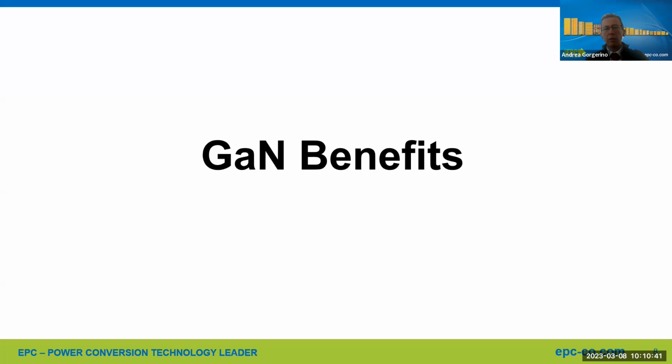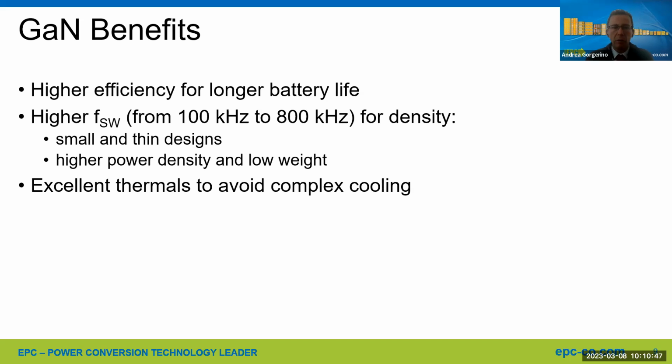All right, so let's dive into some of the GaN benefits for this particular application. I'm going to start off with some high-level topics here. One of the main benefits that I mentioned, one of the requirements from users, is longer battery life. And by having higher efficiency, this is definitely one of the big draws of using GaN semiconductors in these applications, to extend the battery life. But there are also other factors that are extremely important. At the end of the day, it's power density, right? So when you use GaN devices, you can go from a typical switching frequency of maybe 100 kilohertz easily to 800 kilohertz. And this really gives you two things.